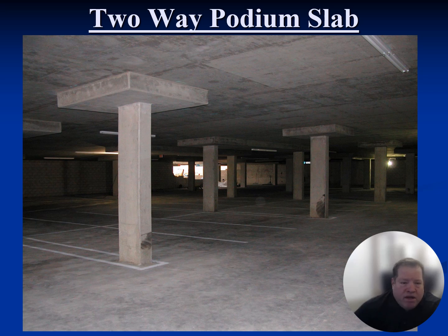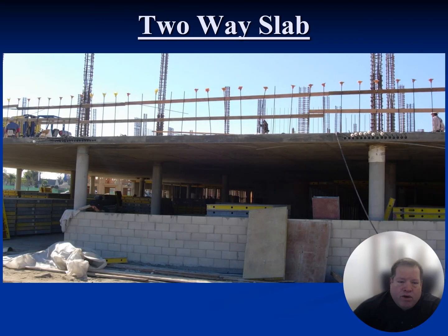But the cap right there is used for punching shear, but also it's used for flexural stress, because obviously your section modulus S goes up, your A goes up, and your d for your rebar design obviously increases with the cap. So while a lot of people would assume that the cap is there primarily for punching, which it does help with, there's also a lot of benefits for flexural, which I'll get into later on.